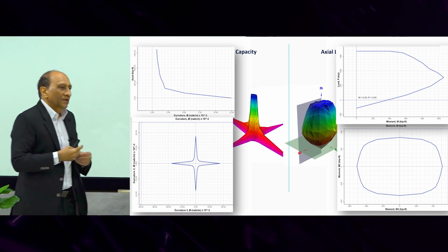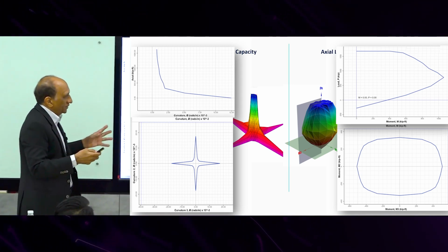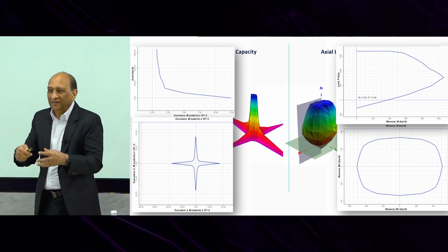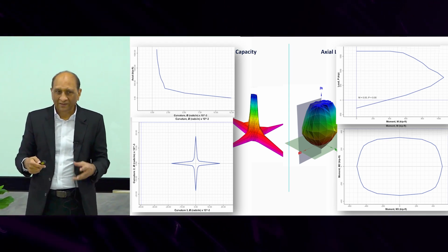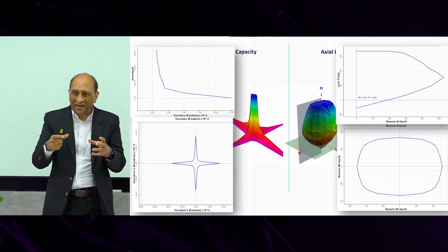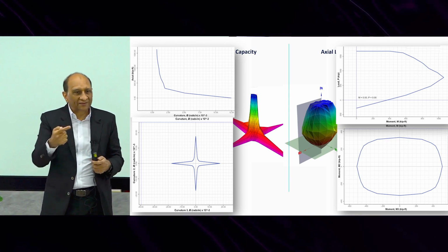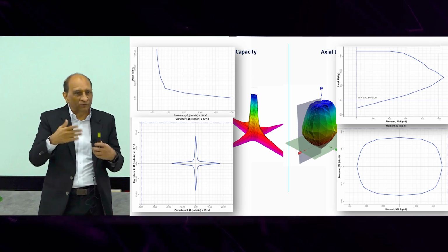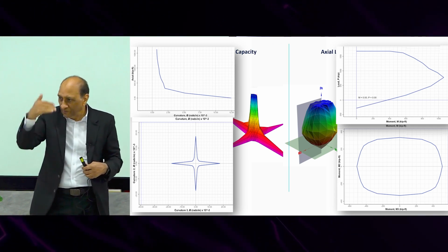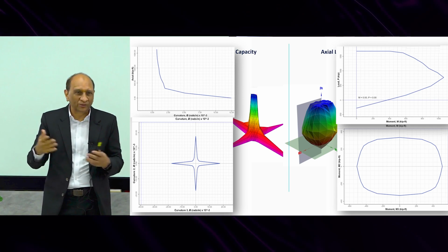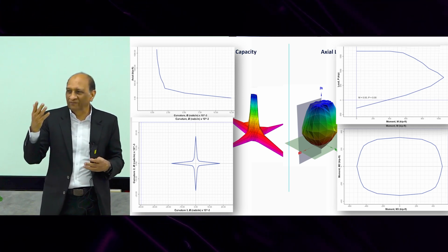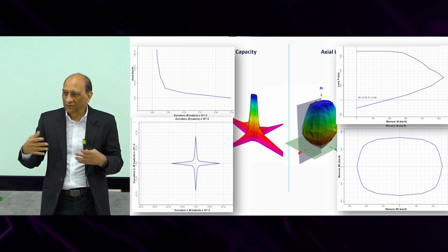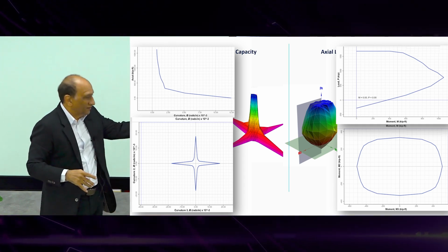So this is the advantage of doing all of this work behind, so you get all this information that you can feed back into your evaluation process. Okay, so when you give SAP or ETABS the fiber section, it generates the moment curvature along many angles. If you don't give that, you have to give them many moment curvature curves at different P, at different angles. You need to give maybe 24 multiplied by 5, but 200 or 100 moment curvature curves to complete this plot that I just showed you.